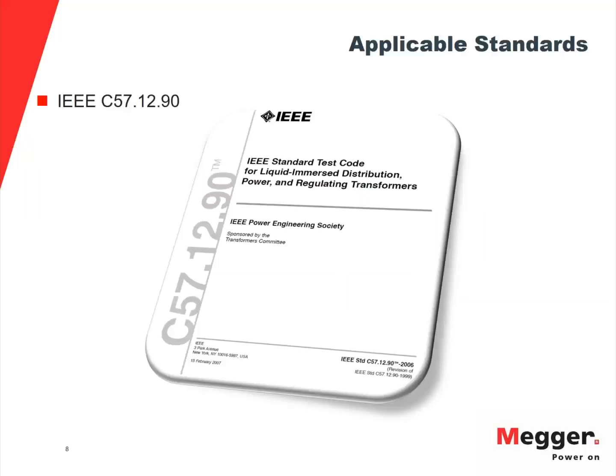There are a number of IEEE standards that recommend turns ratio and winding resistance test. One of those standards is IEEE C57.12.90, and this standard and various other standards provide you the guidelines as how to perform the test and how to analyze the results, and it also provides some of the acceptance limits as well.